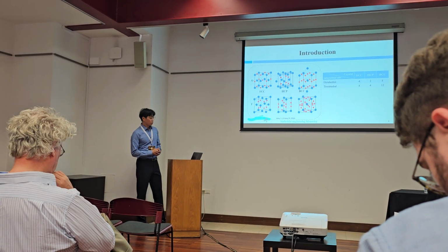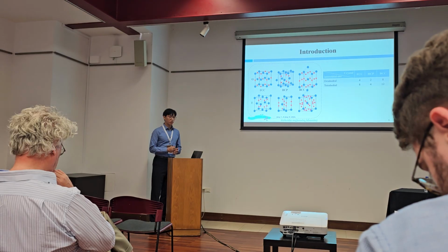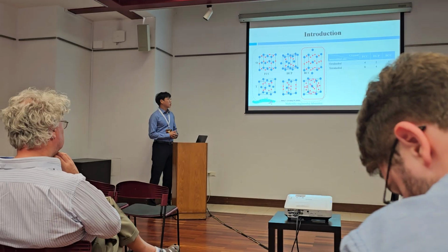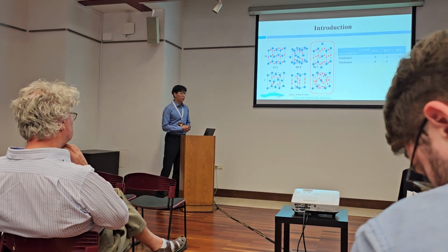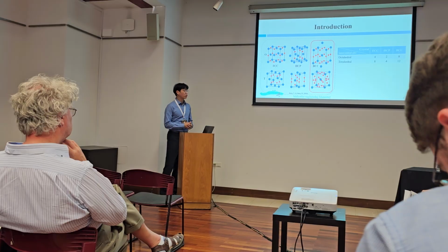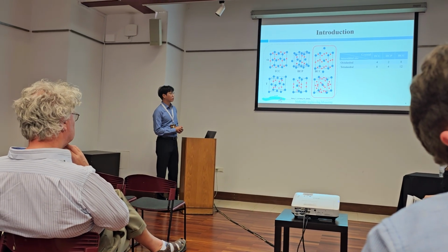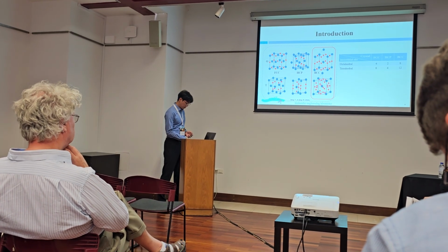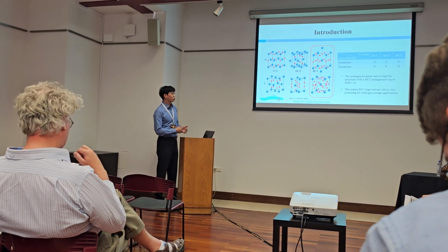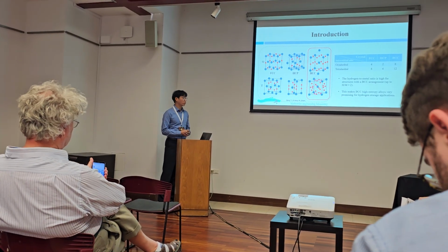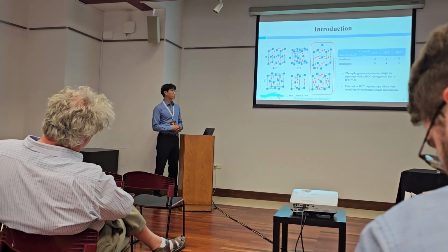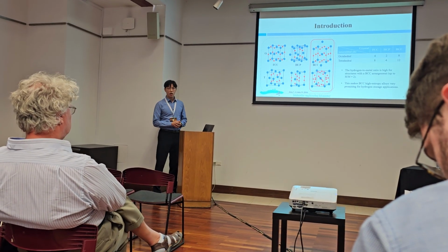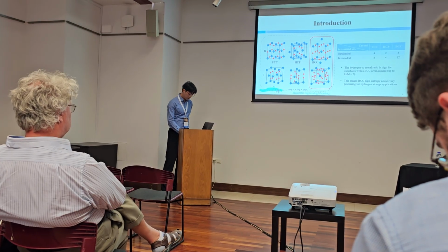This table and figure show why BCC structure is preferred for hydrogen storage. BCC structure has 6 octahedral sites and 12 tetrahedral sites per unit cell, which is more than FCC and HCP structures. The hydrogen to metal ratio is high for structures with a BCC arrangement. This makes BCC high entropy alloy very promising for hydrogen storage applications.